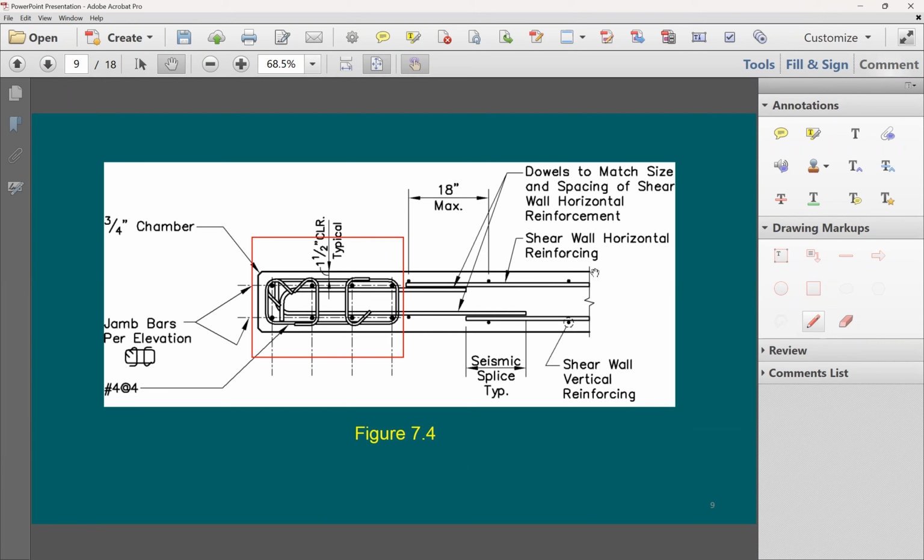So the spacing, which is going to be the maximum spacing to maintain this steel ratio, is going to be 0.31, which is A sub b, divided by As needed. So that gives the maximum spacing. I did the analysis and my maximum spacing is 16.5.